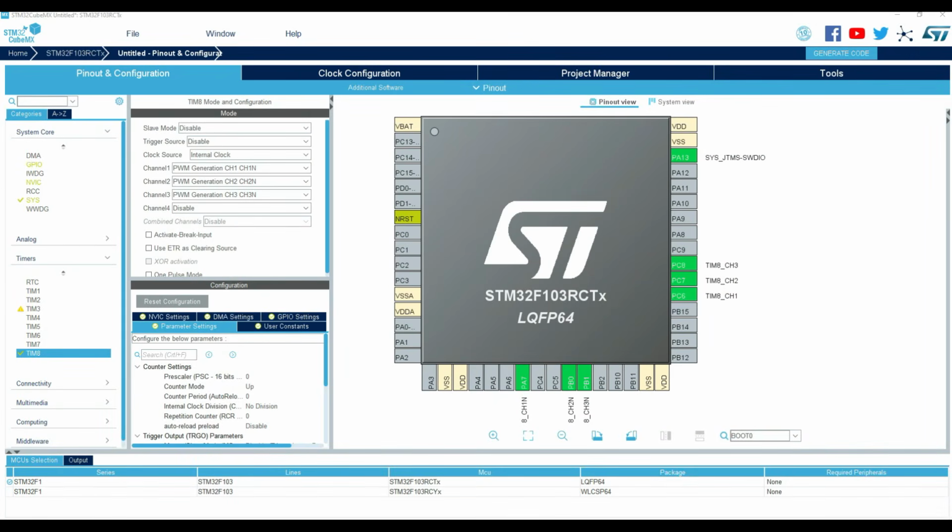The 3 Hall sensors tell exactly when to switch phases. That is called commutation. The Hall signal changes 6 times per full motor rotation. In timer input capture mode, it continuously counts the time between Hall edges and calculates RPM, speed and direction. So precise timekeeping and synchronizing: the motor control loop must run at a fixed interval. Timers trigger interrupts, and code runs instantly.